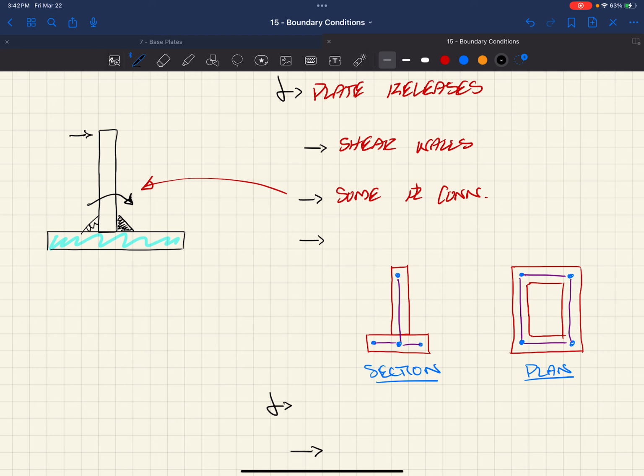If there are demands here and we try to design it with a fillet weld, I go to VA to pull out my demands. All of a sudden, I'm going to have an M, a moment in that direction that the fillet weld needs to take. Shoot, I don't have the capacity, because the fillet weld doesn't have any capacity for a moment like that by itself, single-sided. So then I go back and say, now I need to put this fillet weld out, right?